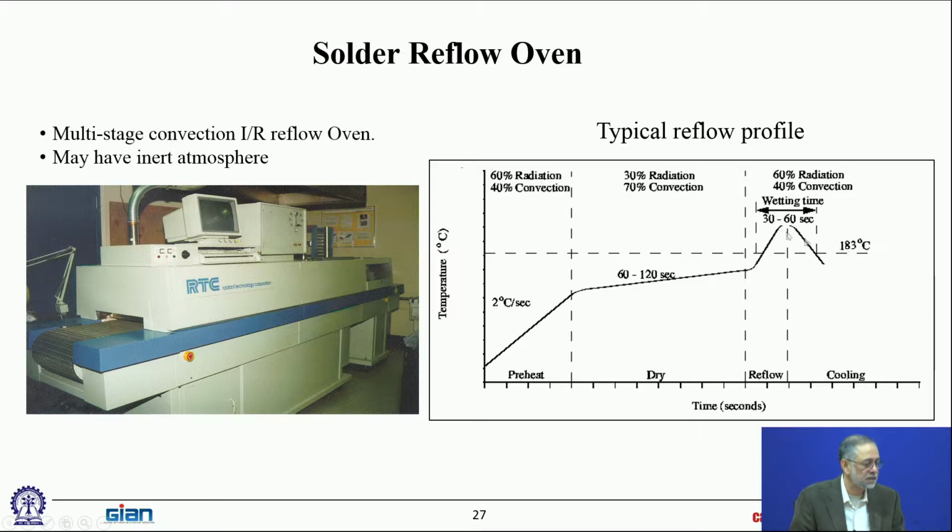So this is for tin lead solder. Melt temperature is 183 degrees C. So you get up a little bit higher than that, about 210 degrees C or so, just to make sure that there are no thermal shadows on the board, or even the ones in the worst thermal shadow of the board have reached reflow. What's thermal shadow? It basically means two things. One, either sufficient energy didn't get in there and it didn't heat up, or there's so many heavy components, thermal inertia in that region of the board, that the temperature didn't reach that high because they acted as heat sinks.